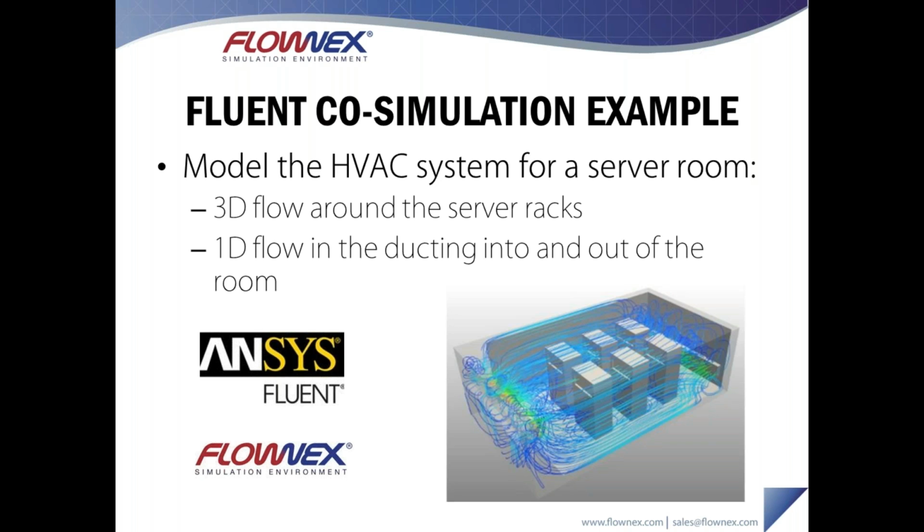So what is ideal is to use a 1D code to provide a means of calculating your conditions at the boundaries to your 3D CFD simulation, knowing measurements upstream of those points. So those upstream measurements are then analyzed using the 1D code, and the downstream results at the boundary for the 3D CFD can be calculated. So it forms a nice way to provide the boundary conditions for your 3D simulations with seamless data transfer.